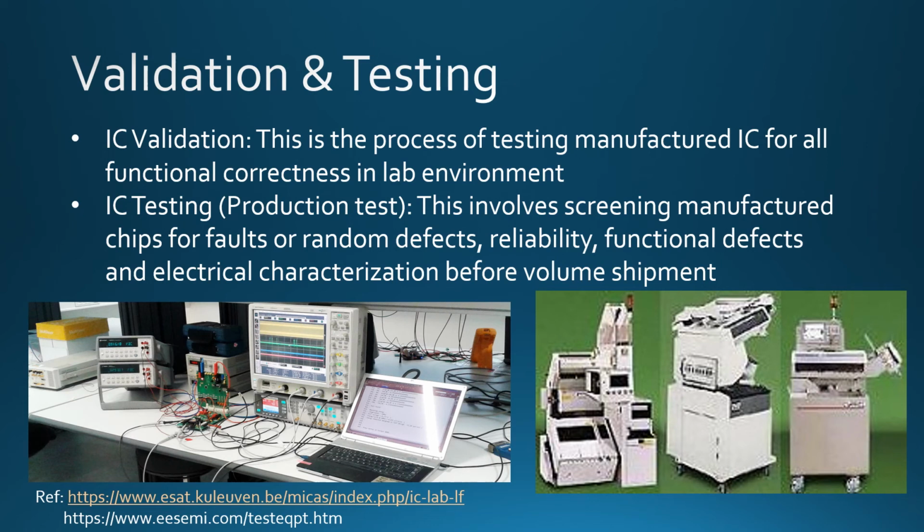And IC testing is more like a product testing, where it involves a lot of software and automated equipment called automated test equipment. There are different types of automated test equipment which will make sure the IC goes through a lot of different combinations. That means there are different modes of operation. They will thoroughly make sure every mode of operation is working properly, and thus we can successfully say that once you pass the product test, you can give the IC for mass production. Otherwise it is not qualified for mass production.